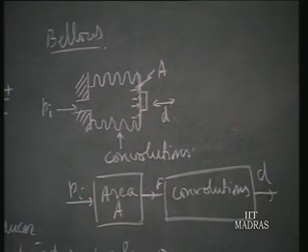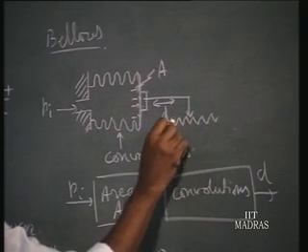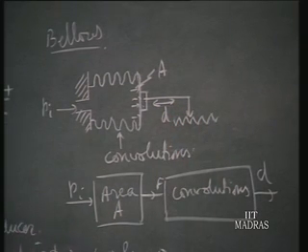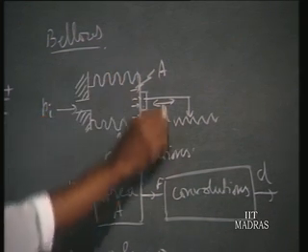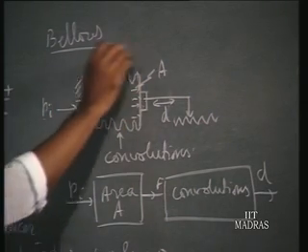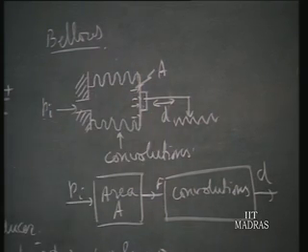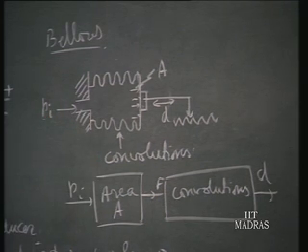This D can be used to move over a potentiometer resistance and convert that displacement into a corresponding voltage signal. So this is for measuring one pressure. If the outside is atmospheric pressure, we measure the gauge pressure. By having a vacuum surrounding the bellows, we can also measure the absolute pressure. We can also arrange the bellows in a way that we can measure the differential pressure.